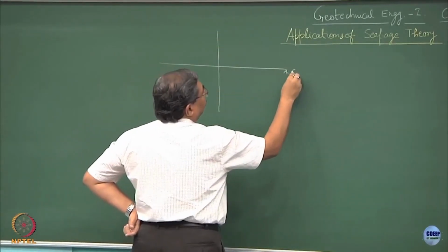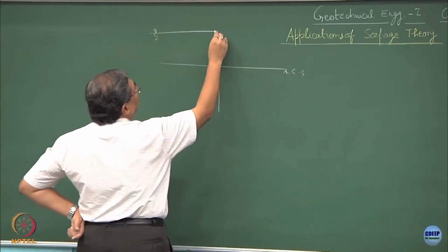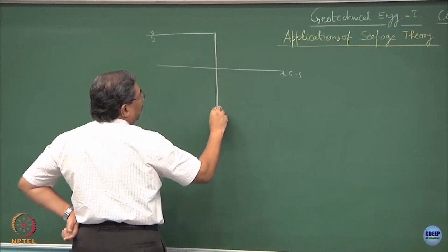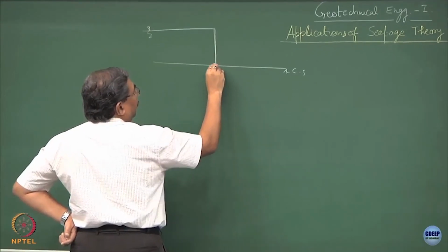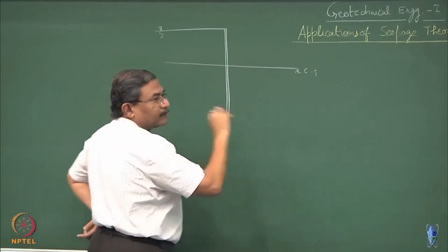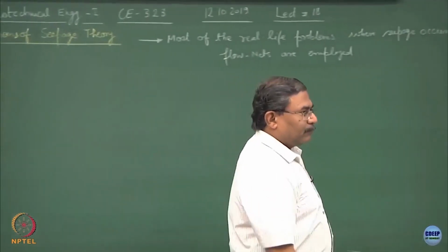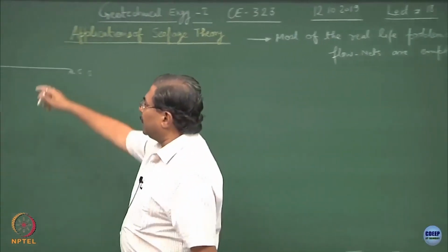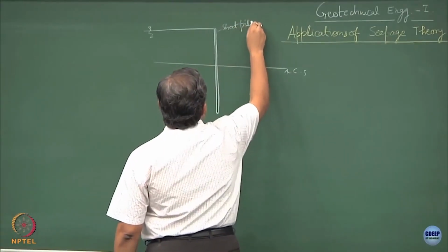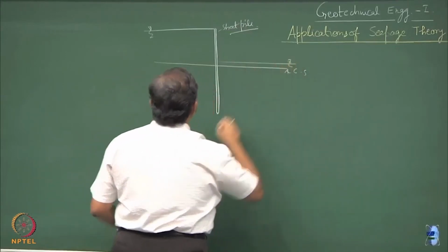So, this is the ground surface, and by retaining this water, this is the sheet pile of certain thickness, certain modulus of, what do we call it, E into I, stiffness modulus. In a structure analysis course, E into I is the stiffness modulus. So, I can select an element, this becomes the sheet pile, and this is how the seepage regimes develop.